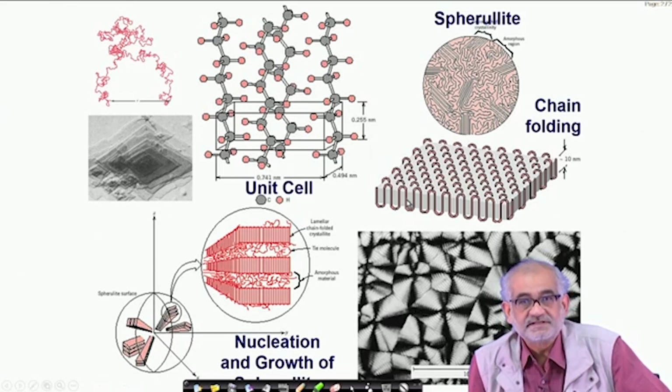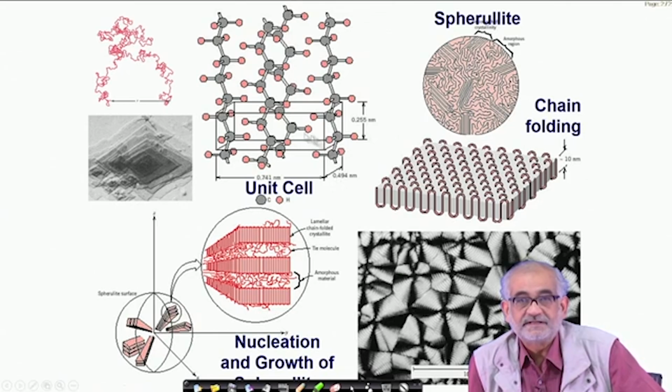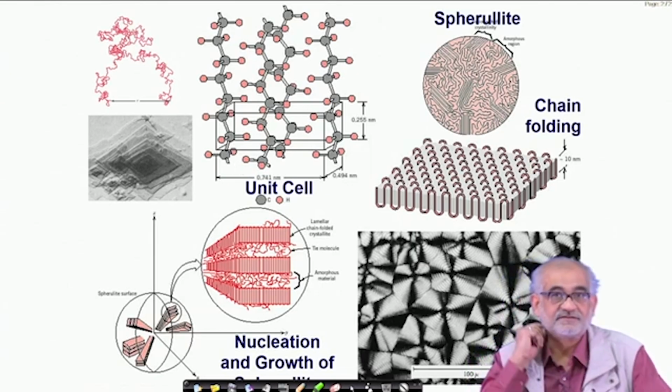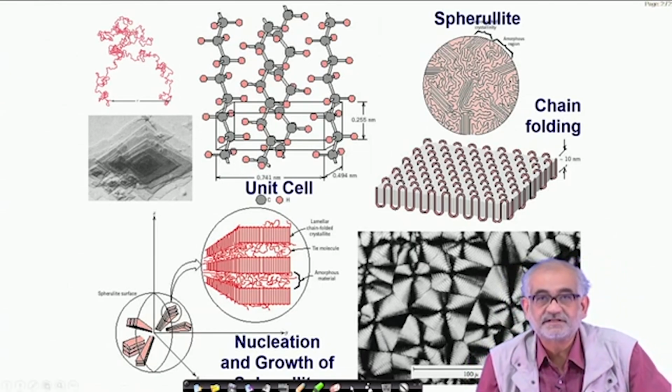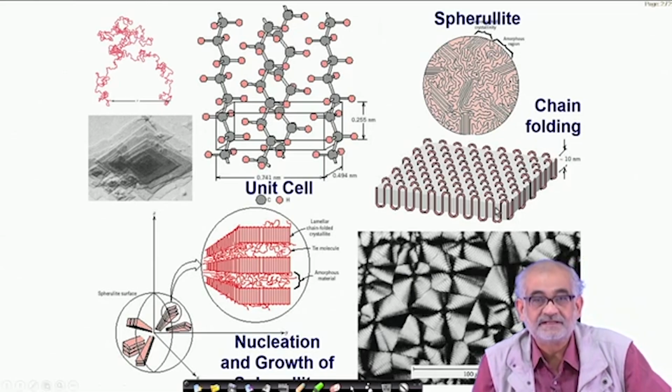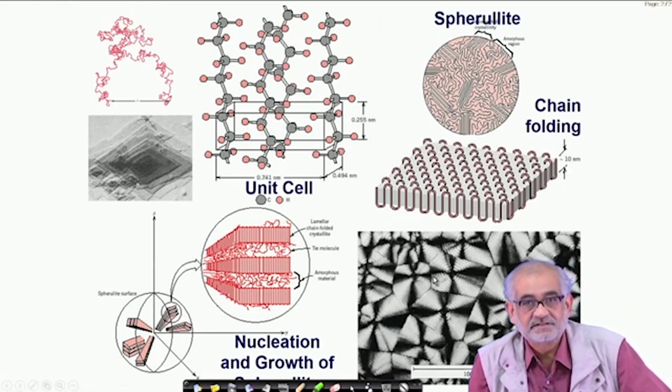But this crystallinity essentially is because of these kinds of layers that are formed. If we imagine that this is a long chain, and if we allow this chain to go through a back and forth chain folding motion, then from point to point there could be certain repetition of the species. If you look from outside, you may see that certain types of atoms or molecules are being repeated at some regular distance in a given direction. And if this directionality continues in 1 dimension, 2 dimensions and eventually even 3 dimensions, then we end up getting such a crystallite grown out of polymeric material.